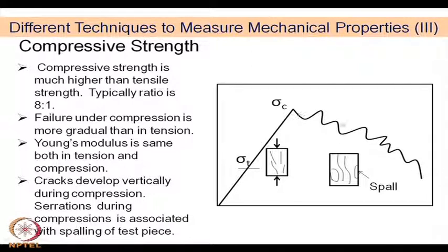However, compared to a normal ductile material, the plastic deformation here is not a smooth curve. It goes through a lot of serrations. So, it represents that the fracture takes place in different kinds of steps. It is not a very smooth regular progression.